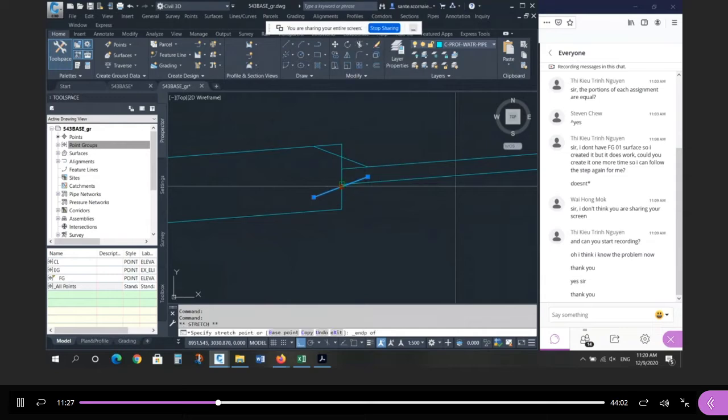Put this over here. Maybe just draw a vertical line from here to here, and from here to here. Intersection here, and intersection here. And then you can kind of trim both pipes. And get rid of that. So that's the reducer, right?